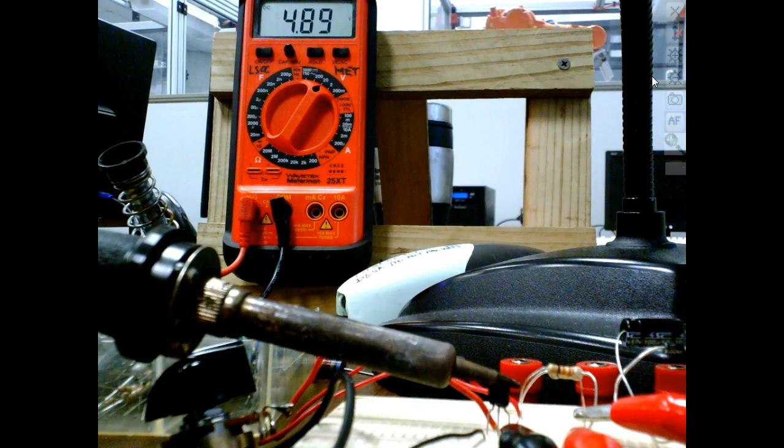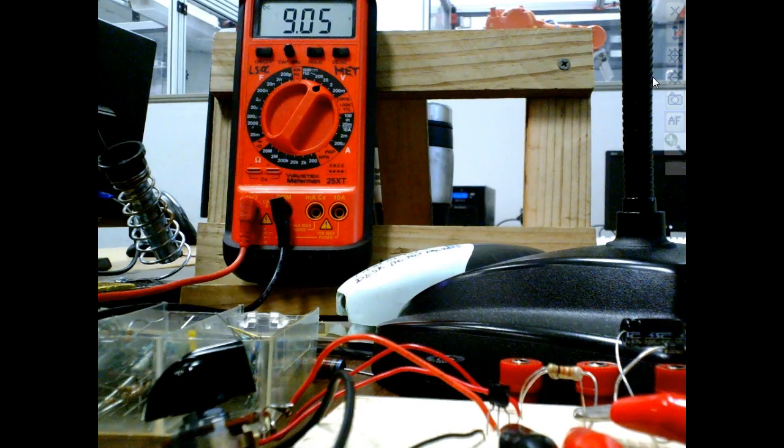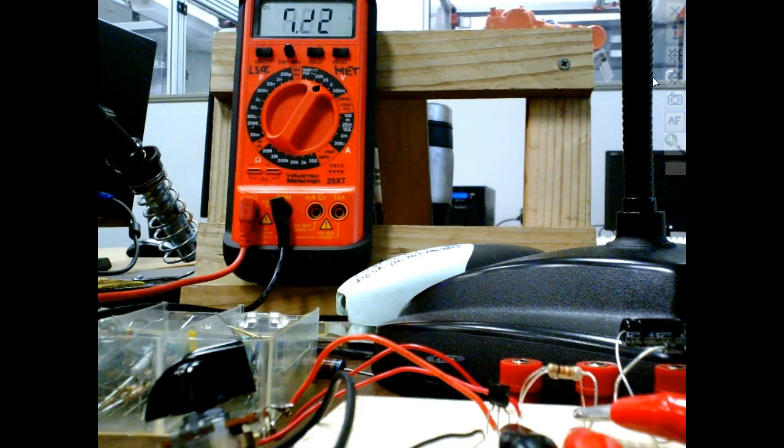Now eventually we could drive this thing into saturation. And then when I take it off, eventually it would start going down. If I hit this with freeze spray, all of a sudden the beta would go way down, right? You understand? And the transistor would drop more voltage. So from this little demonstration, what can we come up with according to beta? What happens to beta when temperature goes up? It goes up.